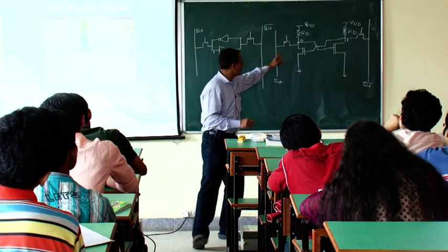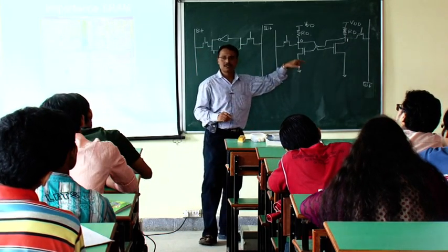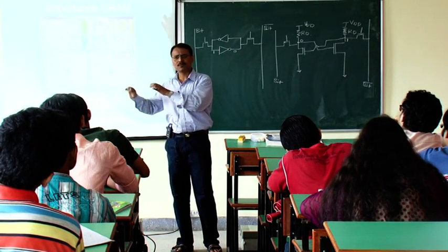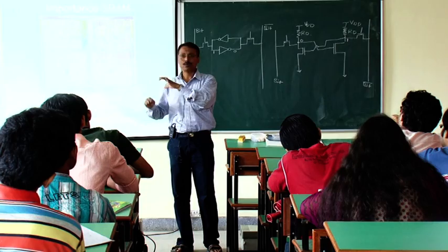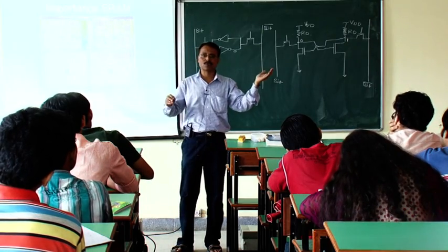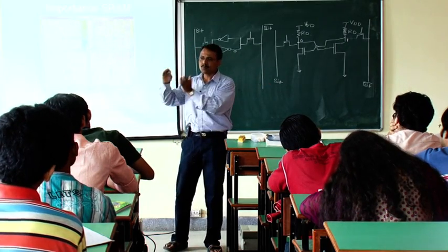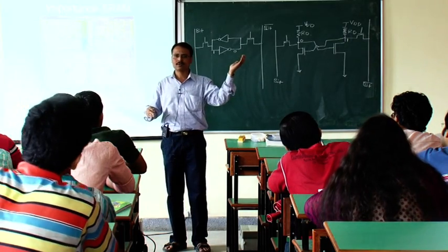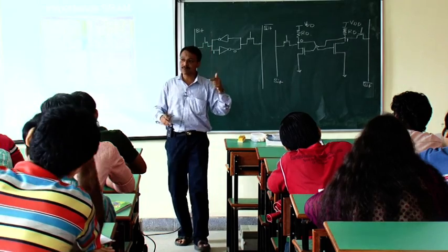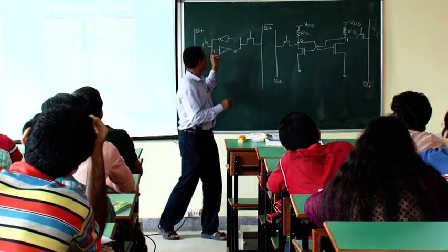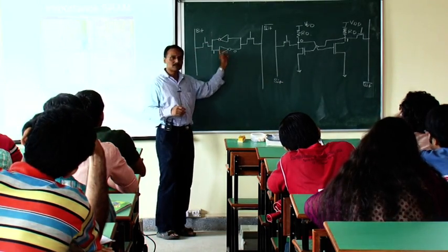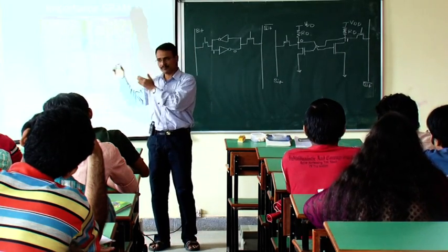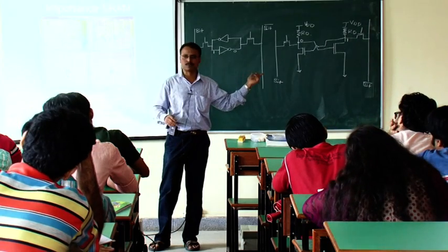The solution is that instead of resistive load inverters, we use a CMOS inverter. We have just studied the CMOS inverter as a single entity. We have not integrated it with any other circuit, yes or no? But whatever the advantages of the CMOS inverter, those are applicable at a higher level also. If I want to design an SRAM circuit, I know that an SRAM circuit uses 2 inverters, and if I use these inverters as CMOS inverters, I can exploit those advantages of the CMOS inverter in the SRAM circuit also, yes or